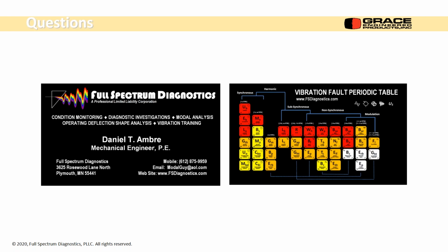So once you get above half the internal clearance and you're vibrating that much, let's say you have 7 mils of internal clearance and you get 4 mils of vibration, you're above that 50% level and you have a better chance of having instability. So you can set off an oil whirl or an oil whip type problem, or just increased wear and looseness. I don't know if that's the exact answer to the question you had, but like I said, everyone, you can follow up with Dan in an email, get your specific answers.